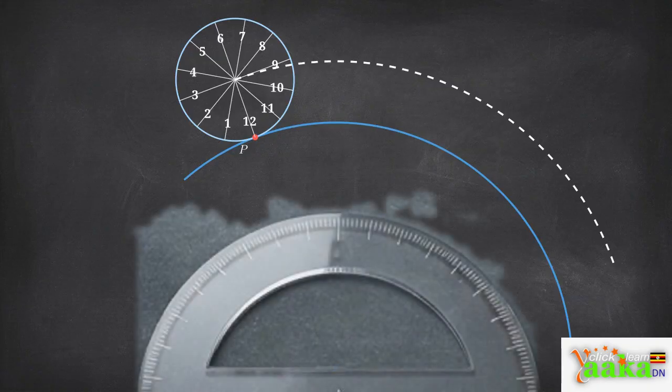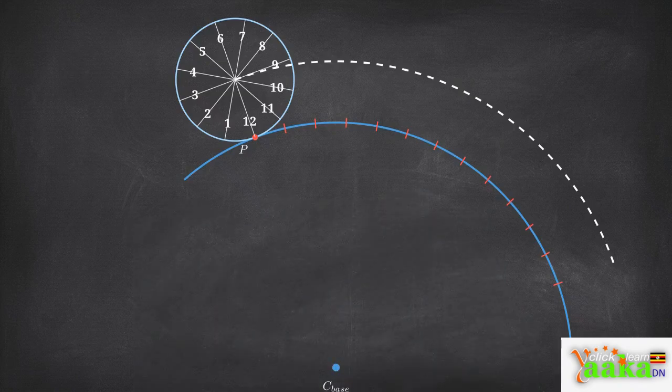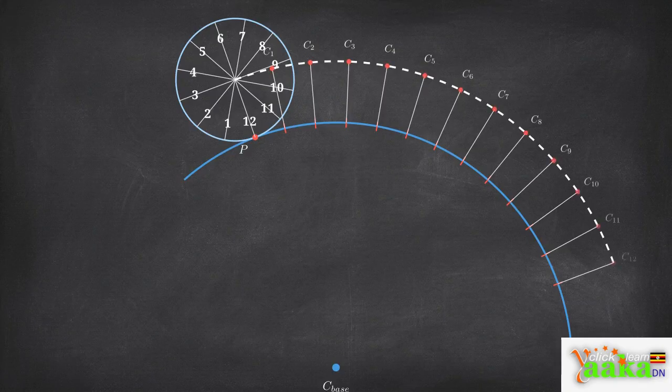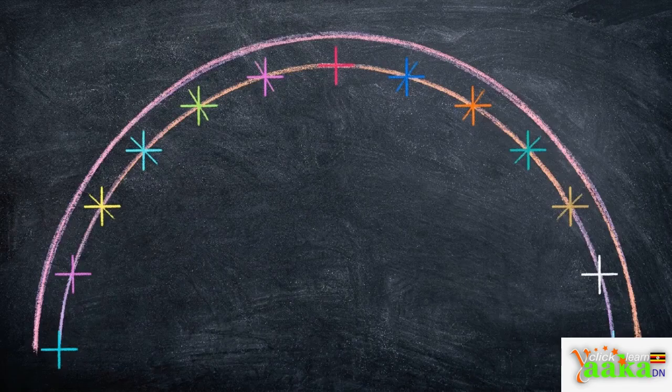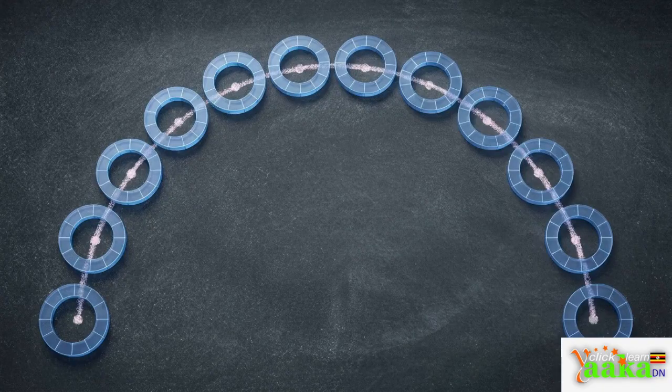Using the theta angle you calculated earlier, measure and mark off those specific degree increments along the edge of your base circle. Project straight lines from those angle marks directly up to your outer center arc to establish 12 distinct center positions. You now have 12 specific points. These act as a time lapse, showing the exact physical location of the generating circle center at every step of its journey around the base.